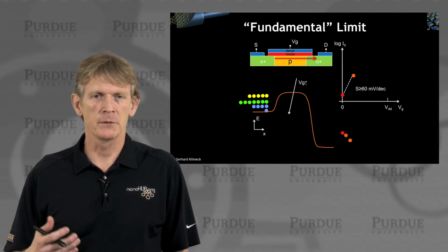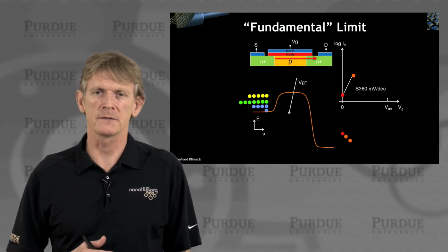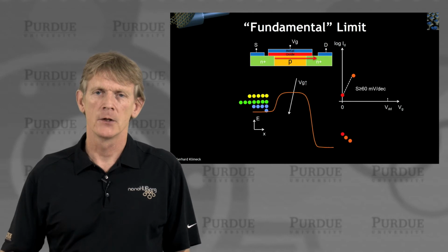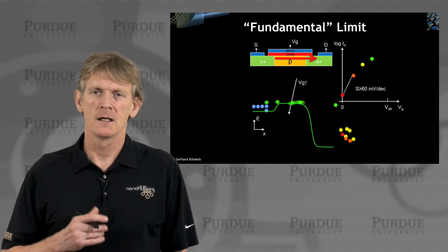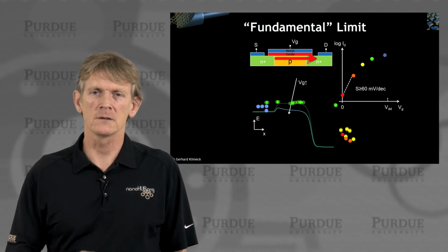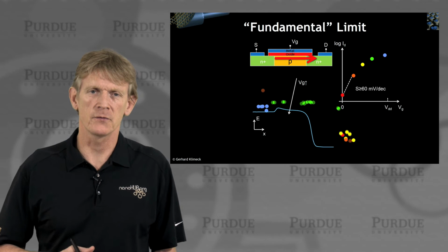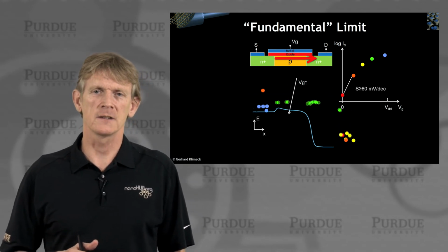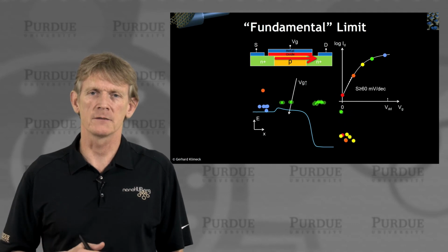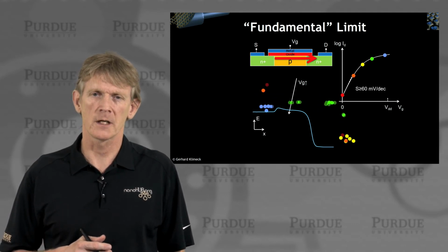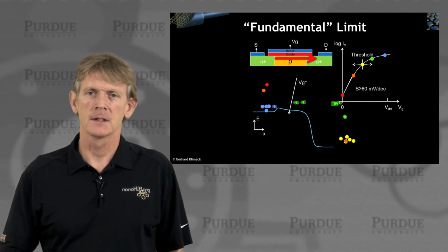And that number should be familiar to you as well, and where that number comes from should be roughly familiar to you as well. So, as you increase the voltage further, you eventually hit some threshold where the channel is really opening up, and then we calculated before saturation currents, etc., and you get your transistor curve that should look rather familiar to you now. Okay, so that's how the transistor works.